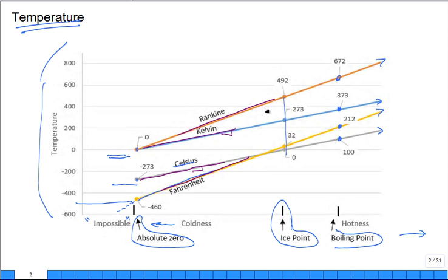And which one's steeper? Meaning that you get a larger numeric value for the same change in hotness and coldness. Okay? So for Fahrenheit, a 1 degree C change is equal to 1.8 degrees, almost 2 degrees Fahrenheit change. It's more rapidly increasing, a steeper slope in the Fahrenheit and the same slope for the Rankine. These two lines intersect because the Kelvin and Rankine are absolute scales. Where do they intersect? 0. They have the same numeric value at the same coldness, the absolute limit of the coldness.